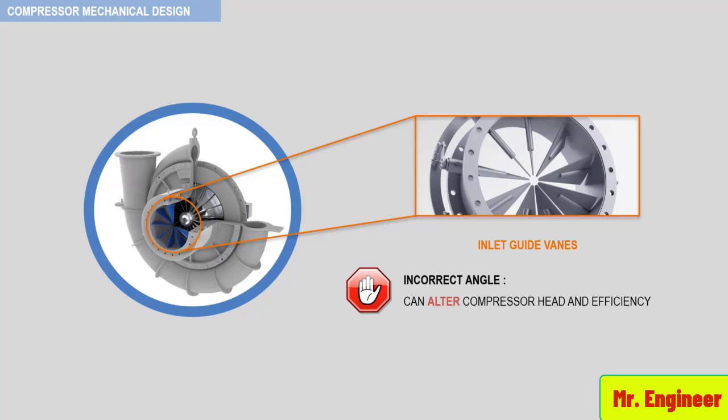However, adjustable guide vanes can be improperly set if the individual guide vanes, bushings or linkages are replaced. So my advice to you, make sure to consult the instruction book and consult the equipment vendor if necessary when replacing any components in an adjustable guide vane assembly.